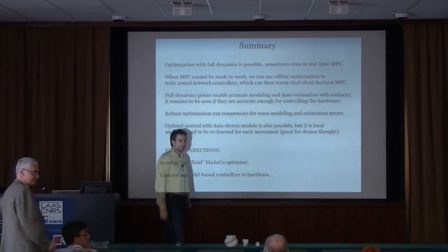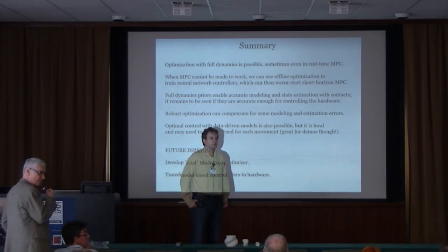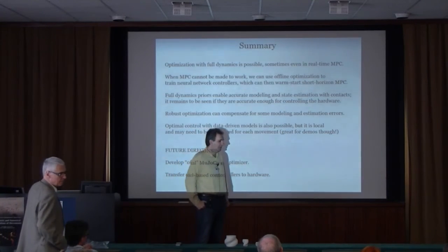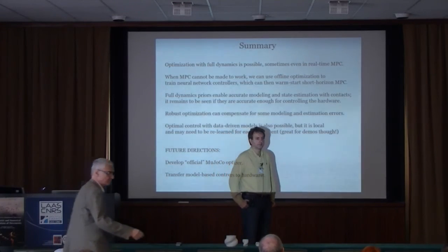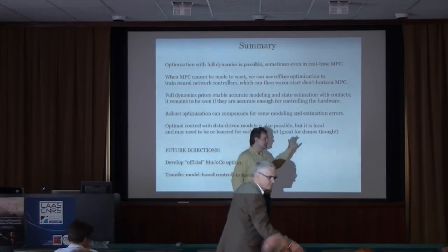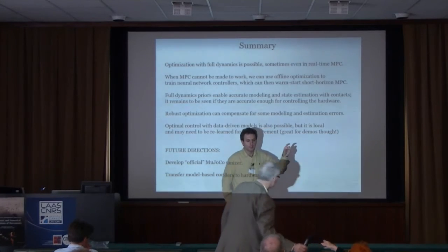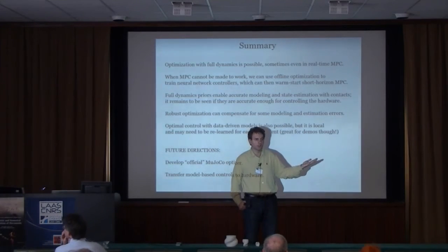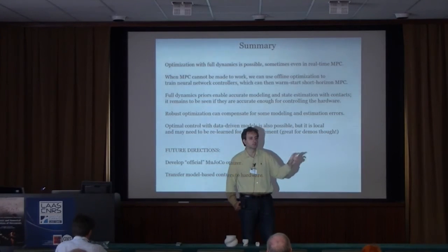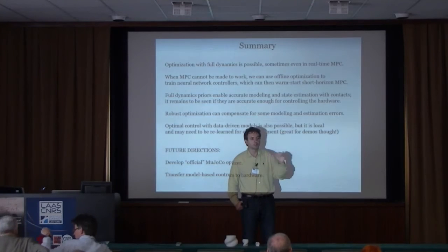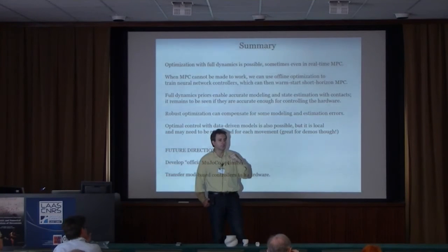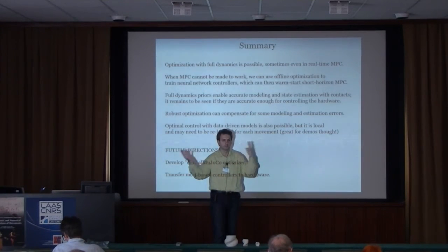Would it be possible to use a similar continuation trick or technique to remove self-collision, or would that create too many local minima? No, we can. In some of those simulations we have self-collisions included. The specific continuation trick that I showed you, you have to declare in advance every contact that you're going to plan explicitly, okay? But you have lots of other contacts that emerge on the fly, and the collision detector is going to respect them and not let you go through them. You just won't be able to do this Jedi trick. Self-collisions usually we don't put in the explicit planner, but it's in the collision detector. So you can collide with yourself, but you cannot push on your hair.